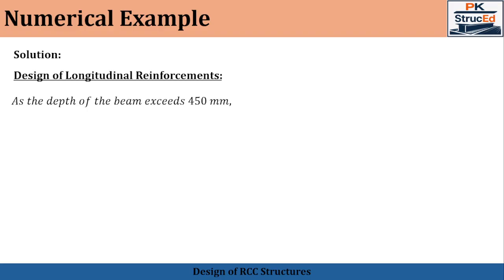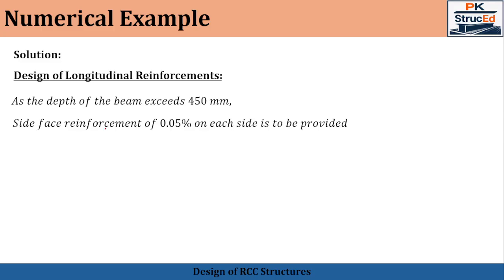Now, as per one more clause of IS 456, consider the depth of the beam, which in this case is 600 mm. Once the depth of the beam exceeds 450 mm, side face reinforcement has to be provided. If D is greater than 450 mm, side face reinforcement has to be given. So in our case, D is 600 mm. Therefore, it is a must that we provide side face reinforcement. How much side face reinforcement is to be given is 0.05% of the area.